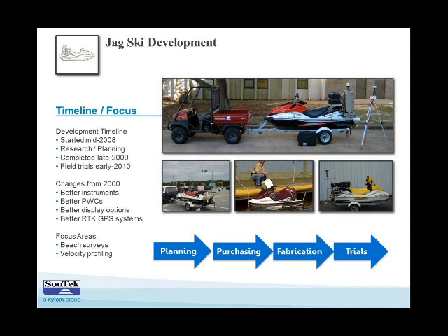So with our Seakeeper system, it continuously samples the water and records those measurements. And so over the 7.5 hours, we continuously collected over 2,000 water samples and did some physical sampling as well, and stopped and kind of hovered around some of St. Johns River Water Management District's long-term historical water quality monitoring sites, and doubled up on measurements there for them. So just a little anecdote of surveying and mapping water quality with the Jag Ski.